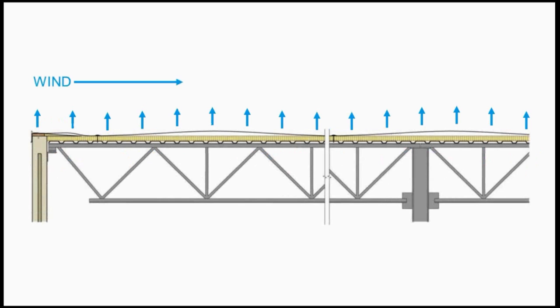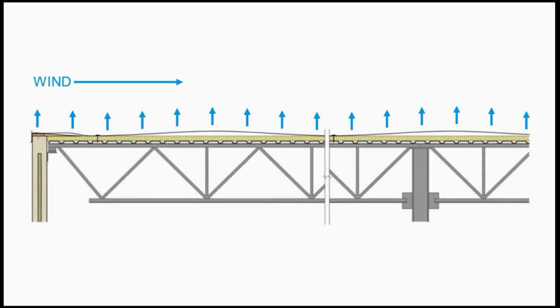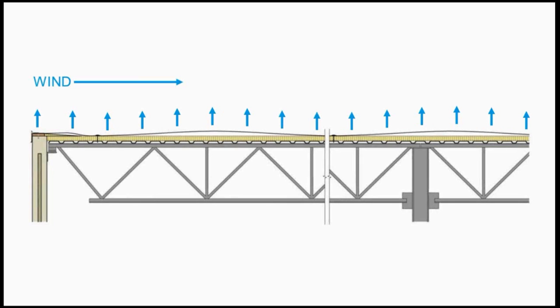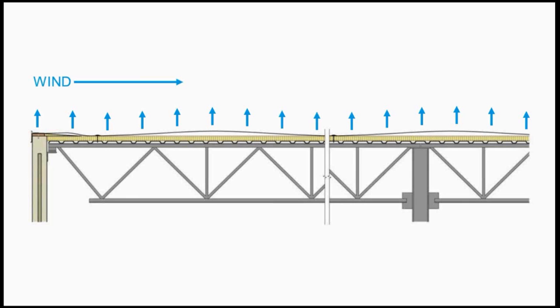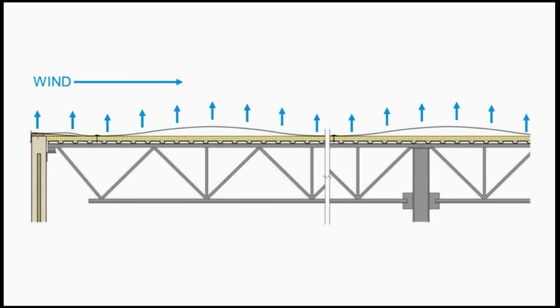So what you basically have is, as the wind goes over it, it pulls air in from the inside. Now, if it dies back down, that air gets pushed back out. The problem is if that membrane is cold, that air lost its moisture when it was in the up situation, and when the air was blown out, it fills back up with fresh, moist air, continuously increasing the thickness of that frost layer. And that's what we call pumping action, because you're basically not developing an airflow path. You don't have an airflow path from the interior to the exterior.